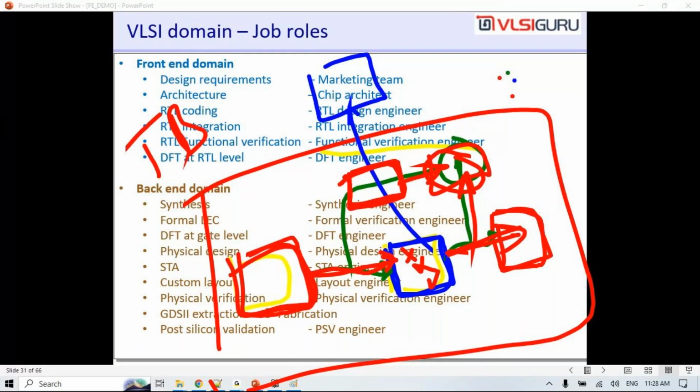So, if someone is working in the field of functional verification and later wants to switch to RTL design, how can one do that? What else do you need to know for that? The first thing is he needs to look at things from a synthesizable perspective. See, when I develop this test bench, whatever you see in the red box, I don't bother whether it can be converted into gates or not. I will develop it because I have no requirement to convert it into gates. Whereas anything that is developed in this blue box needs to be converted into gates. It should be synthesizable. So I have to look from the perspective of how to develop code which is synthesizable.